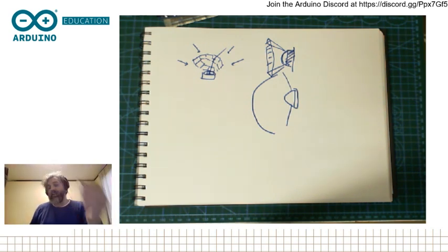So I'm going to use the Parallax sensor, just because it's easier to use. And I'm going to explain this because it might take you by surprise. These sensors that you can buy very cheaply sometimes work with an open collector and sometimes don't. If they do, you still need a resistor to mount this thing, and it's very confusing because you never know if it's a pull-up or a pull-down resistor. If it's an open collector, it's typically a pull-up resistor, but you never know. But here we have this Parallax PIR sensor that just gives you a straight output that you can use.